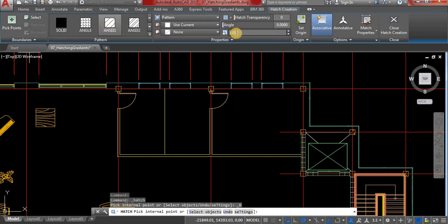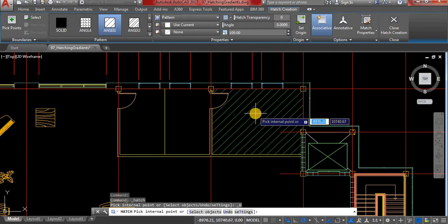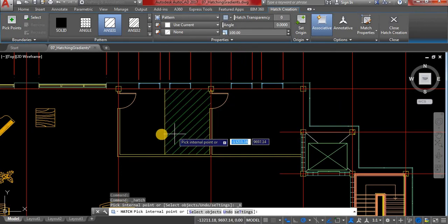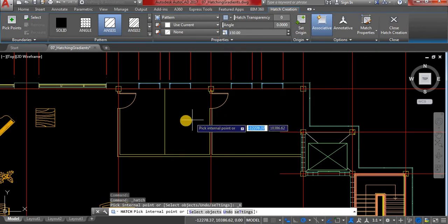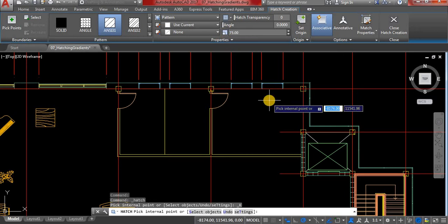and this is the scale. It's 1, so each 1 millimeter is gonna put a line. We're gonna change it to 100 first and press enter. When I go down, you see it gives these parallel lines of the hatch. Let's just try 150 and see what happens. You see the spacing is different. 300. Definitely more space. I think 75 would be okay. Yeah, I'm happy with this.